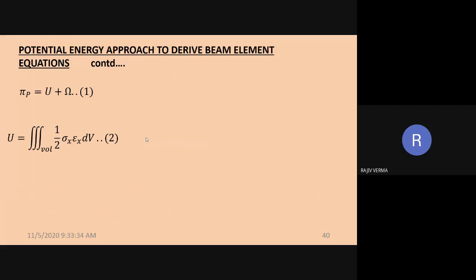Please note that the same formula was used for finding the internal strain energy for the case of the bar also. This is because both the bar and the beam primarily have only the stresses and strains acting along the x direction. Other stresses and strains happen to be of no significance. This obviously comes from the elementary SOM theory.